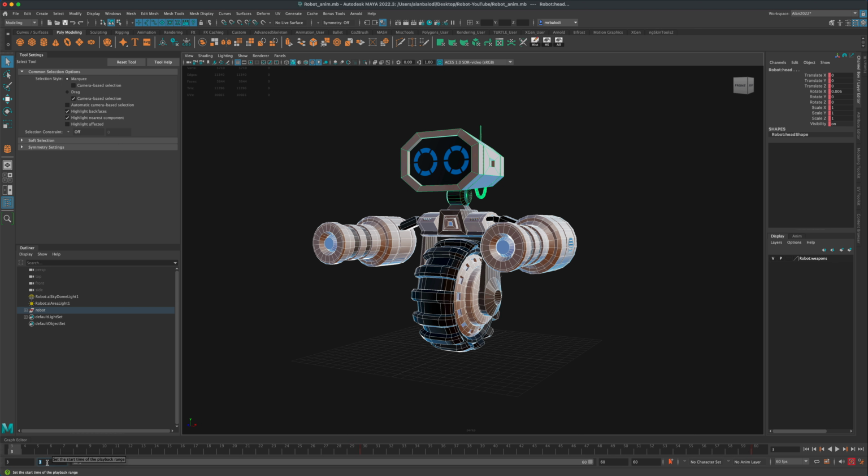and if you wanted to go back to 1, just press 1 and press enter, and you can see that your first keyframe is right there. Now when you do adjust the frame rate like that, a lot of times the keyframe will get positioned between the full numbers, so between 2 and 3. It looks like it's at 2.5. So to fix that, you have to right click and go to snap. And once you do that, you can see that it snaps into place. I can now hold the shift key and move this around. I can put this back to 1 if I wanted to. I want to make sure that my keyframe 1 and keyframe 60 are at the same position.